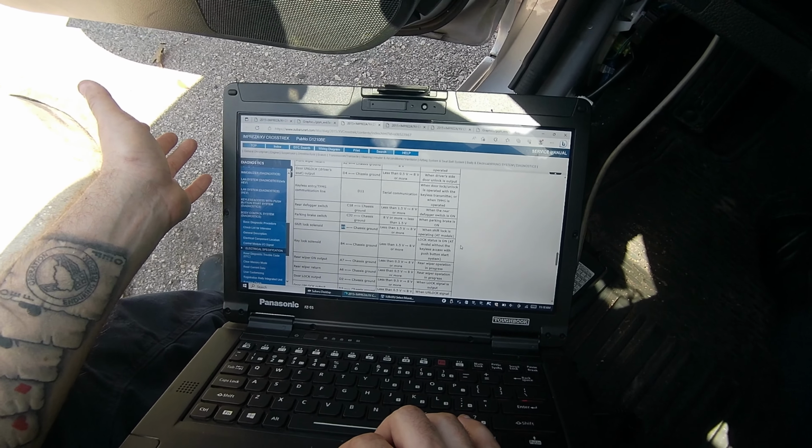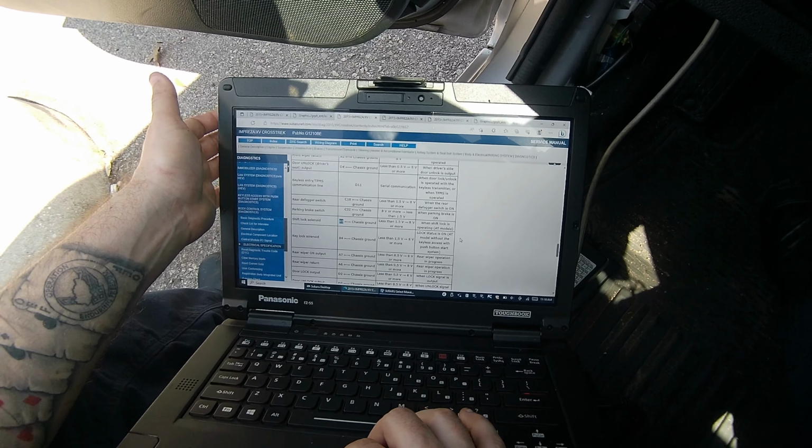So basic square wave that I'm looking at, and this column up here reads ignition switch on, engine off. So we can test this without the engine on. So at rest I should have less than 1.5 volts, which I did, but stepping on it to get the other condition I should have 8 volts or more. So obviously this is a 12 volt circuit. So I'm not getting my 12 volts out.